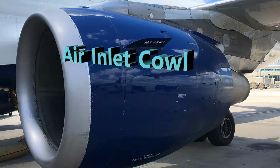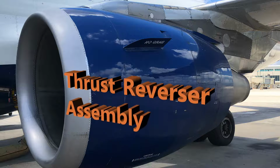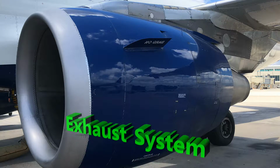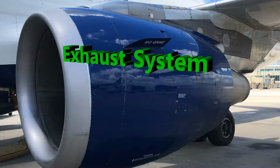There's also your thrust reverser assembly that has two halves. Those two halves are also referred to as C-ducts, D-U-C-T-S, and those are attached to the pylon and have translating sleeves that move, so be careful with all of that. You have an exhaust system that has three sections. You have forward and aft exhaust nozzles as well as an outer exhaust nozzle.